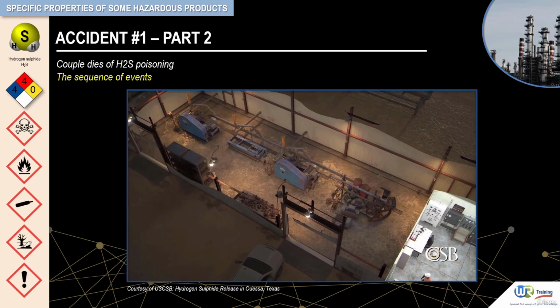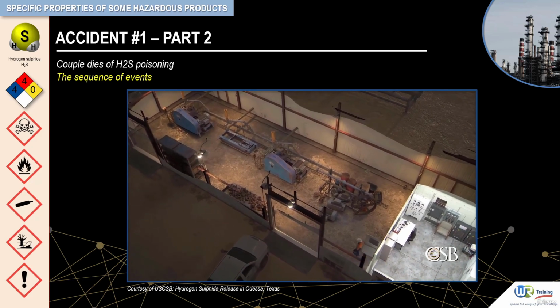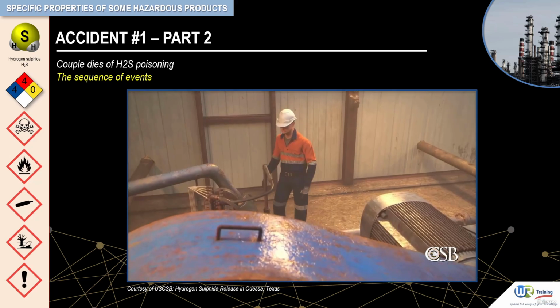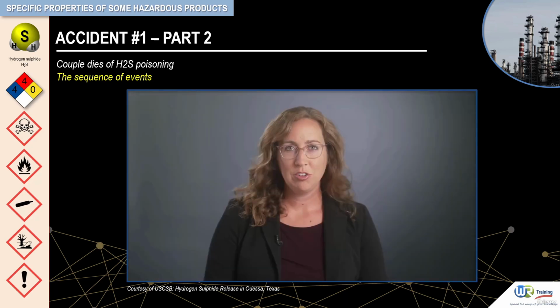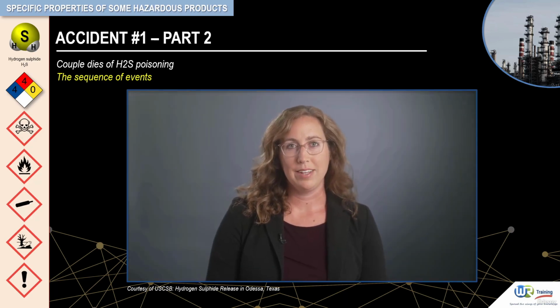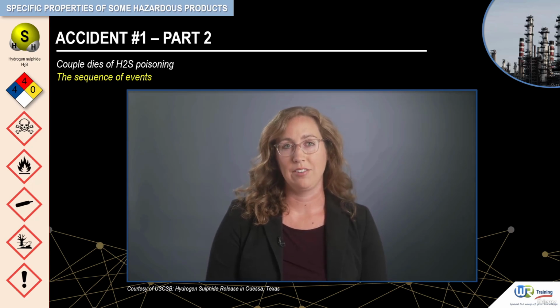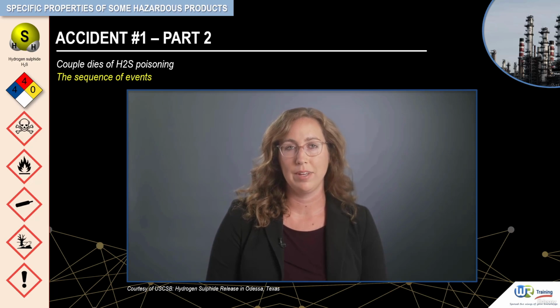However, there was no evidence that Aghorn management required use of personal hydrogen sulfide detectors or adequately trained employees that equipment malfunctions could indicate a toxic hydrogen sulfide release. Companies should ensure workers always use the required safety equipment, such as personal detectors, when entering a potentially hazardous area. Regular training and posting signs will help remind employees to use their safety equipment every time.